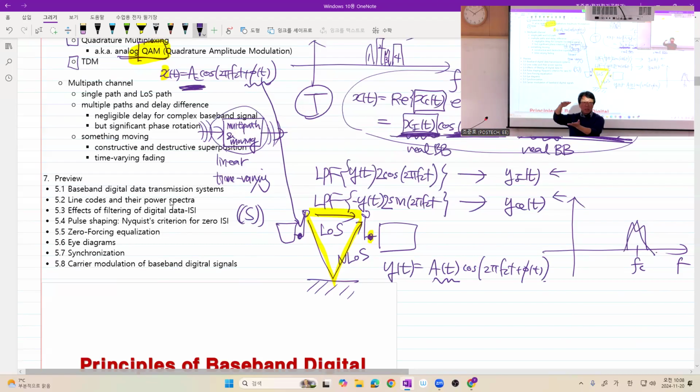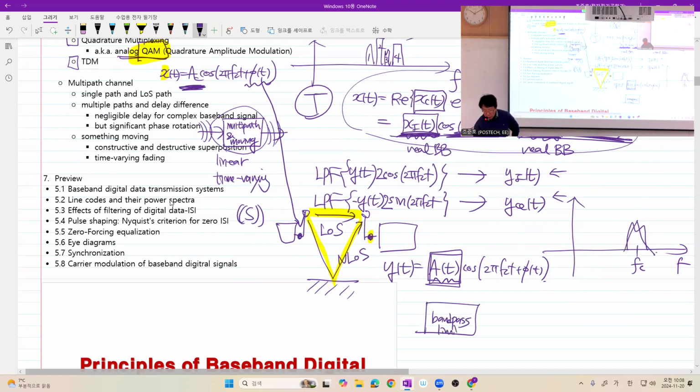In that case, what happens? Without a bandpass limiter, our FM discriminator or FM demodulator based on a differentiator followed by an envelope detector may have a lot of distortion due to this time varying amplitude. That's why we had what? Bandpass limiter, which is a combination of limiter and bandpass filter before our ordinary FM detector. Got it?